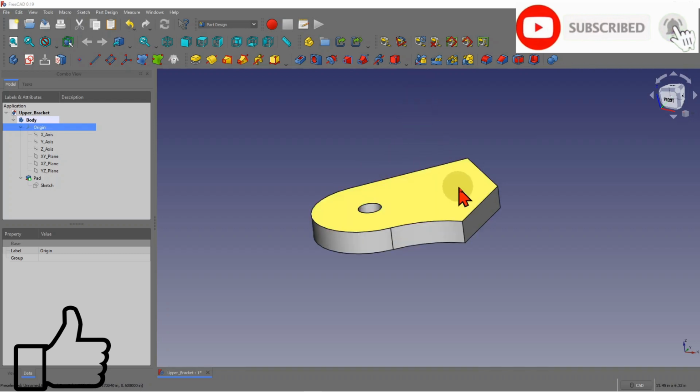So the alternate solution is, rather than creating a sketch on this face, to create a datum using the original planes and move that to align with this face, okay.